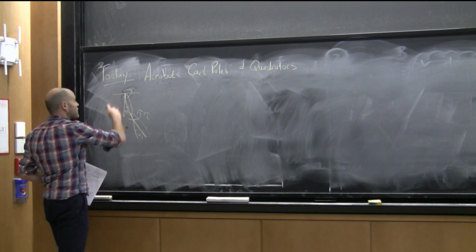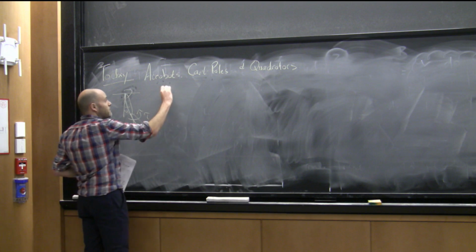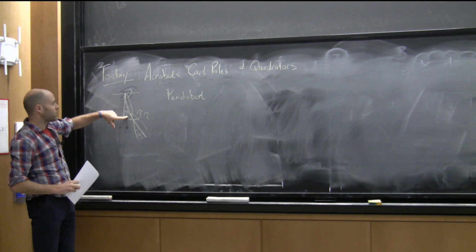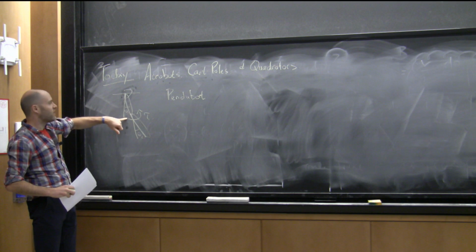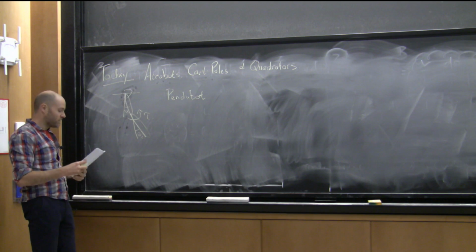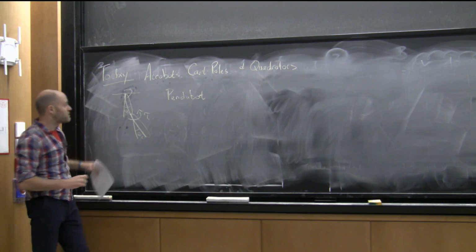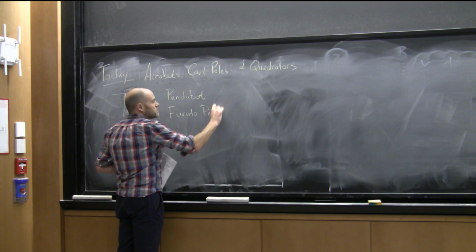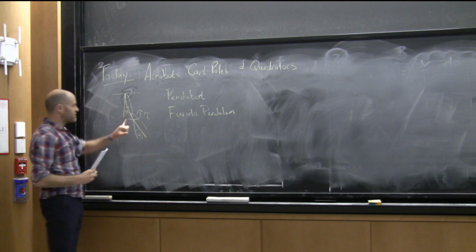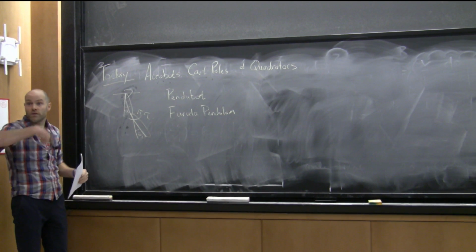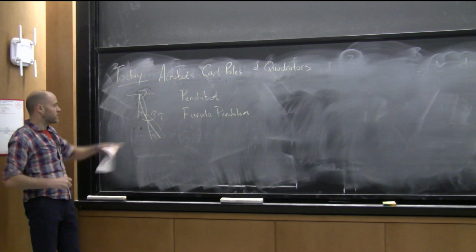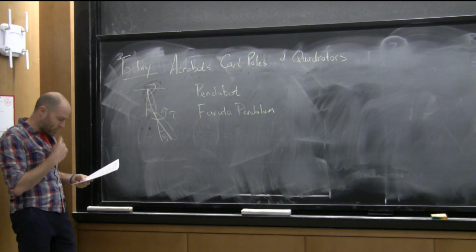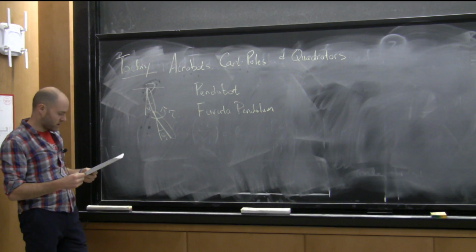So that's called the Acrobot. There's another version of it called the Pendubot, where someone stole the actuator from here and put it here, but then left the elbow off. That's just called the Pendubot, but that's out there too. You can do some of the same games. There's the Furuta pendulum, which is almost the same, but you take the second link away and put a reaction wheel there. You might have seen that one where you've got a spinning mass on the end, and you've got an actuator there. So it's almost the same. It's just that now your inertia is centered at the joint. Reaction wheel pendulum is another name for these.